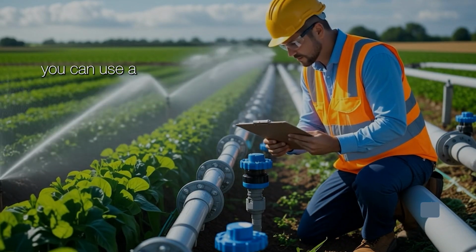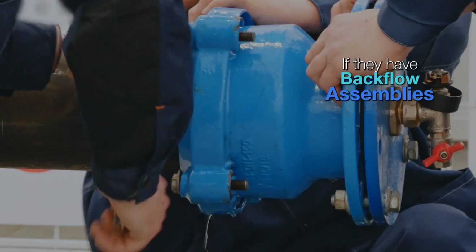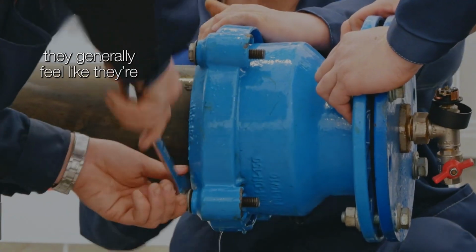What can we use a double check for? Well, double check right now in the state of Texas, you can use a double check on your irrigation for non-health. A lot of utilities or water purveyors have their records, and if they have backflow assemblies installed at a site, they generally feel like they're protected. If I'm a facility and I have a backflow assembly installed, does that automatically mean I'm protected? Absolutely not.